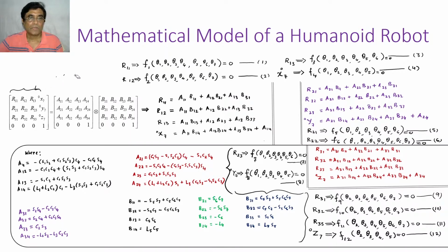Now on the right hand side also, after this multiplication, you will have a 4 cross 4 matrix. Proper would be to denote them with some other notations, but I think it is to be clearly understood. So these are my R11, R12, R13. And what is this? This is actually your position vector, and this 3 cross 3 is your orientation matrix. This describes your orientation, this describes your position, and this is the scaling row, giving you nothing, just to homogenize the matrix.